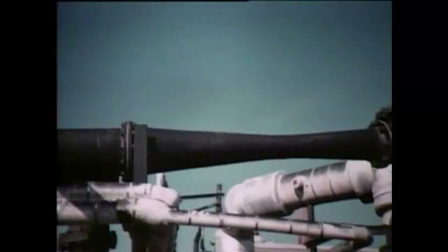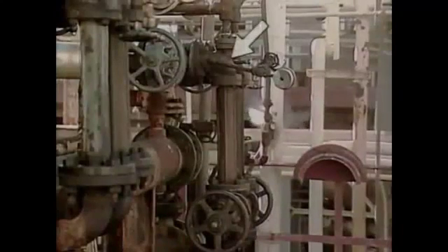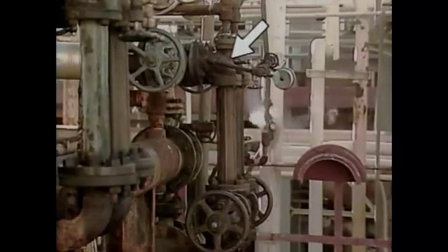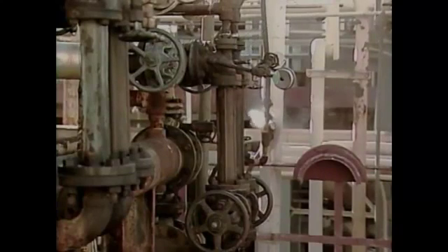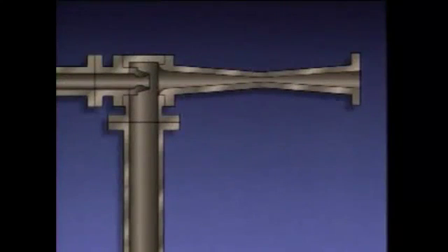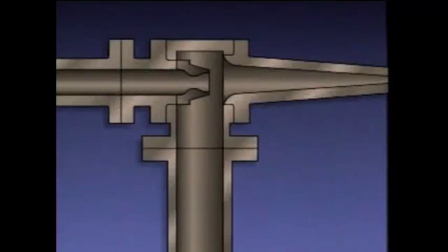Another component that's used in liquid as well as gas and vapor systems is a jet pump. A jet pump uses the flow of one fluid to move another fluid. An air ejector that uses steam to remove air and other non-condensable gases from a condenser is one type of jet pump. There are no moving parts inside a jet pump. Instead, the pump relies on energy conversions to operate. The jet pump shown here has a nozzle, a pump inlet, a combining chamber, and a discharge section.